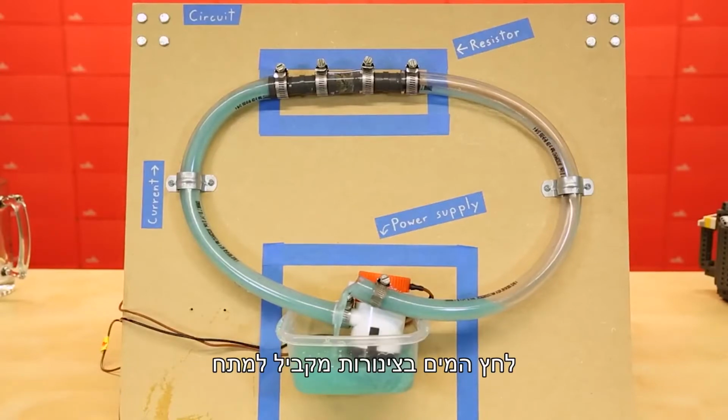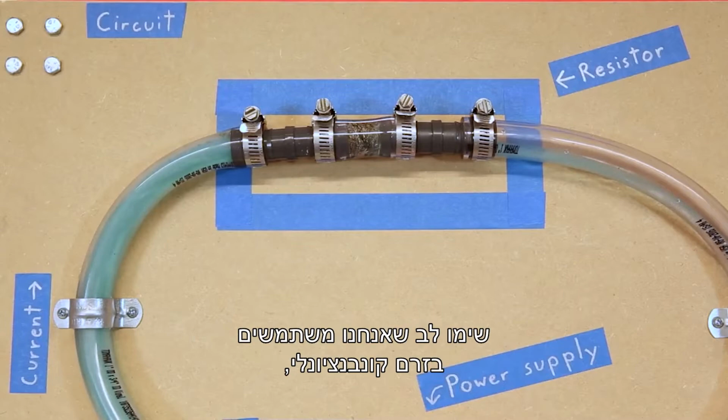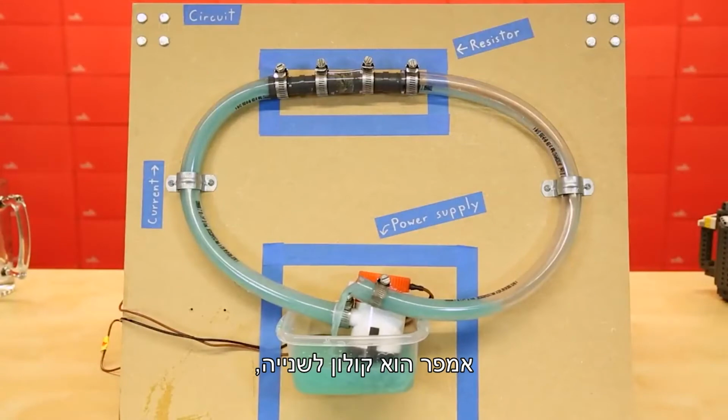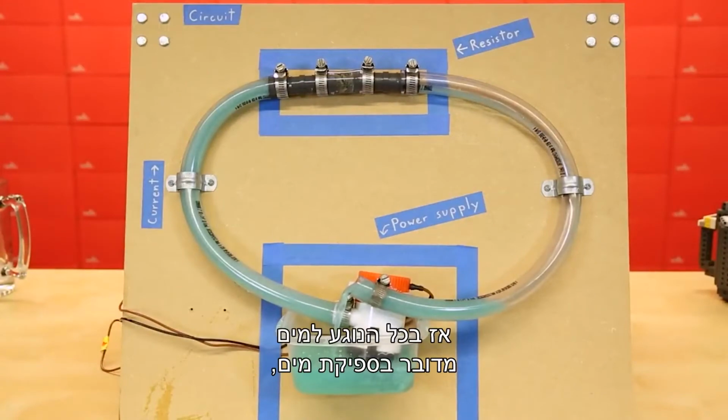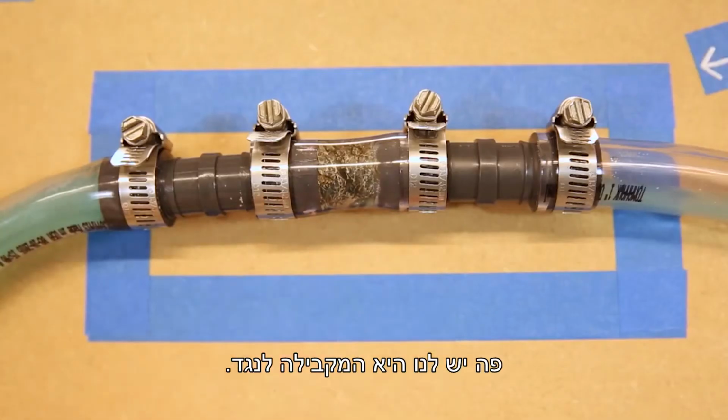The water pressure in the tubes corresponds to voltage, and the amount of water moving through a tube corresponds to electrical current. Note that we're using conventional current, so the water is flowing from high pressure to low pressure. Amperes is coulombs per second, so in terms of water, that would be volumetric flow rate, something like cubic centimeters per second. What we've got here is the water analogy of a resistor.